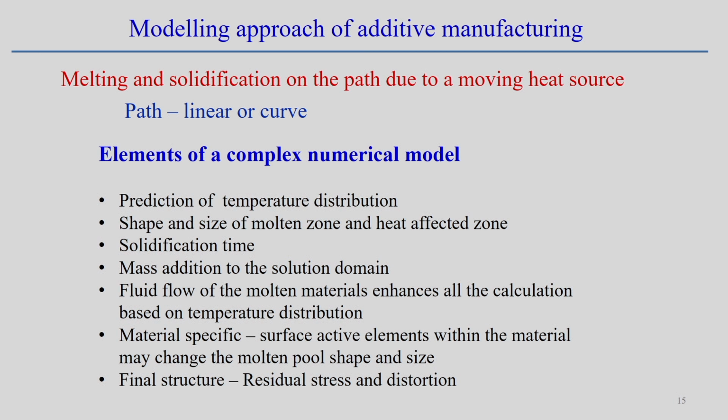So it is basically to enhance the calculation accuracy associated with heat transfer in the additive manufacturing process. Now, the final structure: heat transfer analysis, material flow analysis, the free surface flow, the free surface profile. Apart from this, finally after solidification, what can be the stress level and distortion level in the structure? That can be done simply by performing the thermomechanical analysis, which normally predicts the residual stress and distortion.